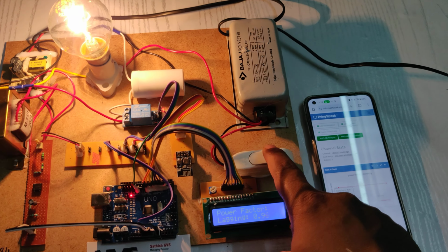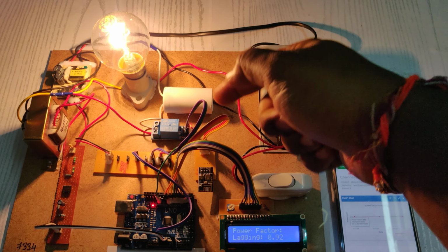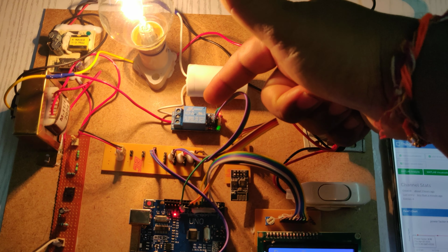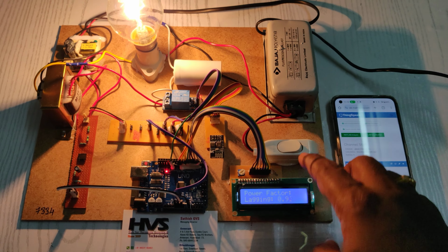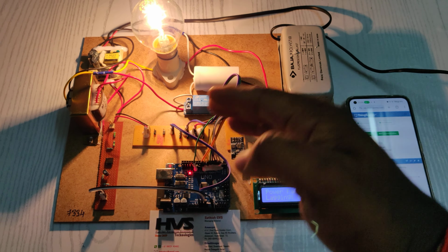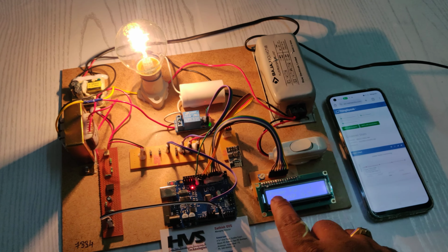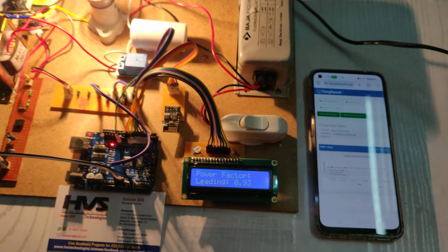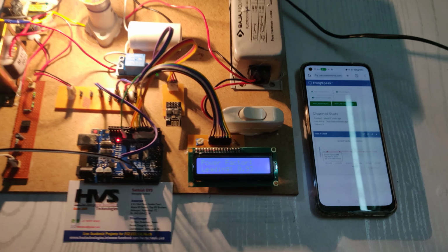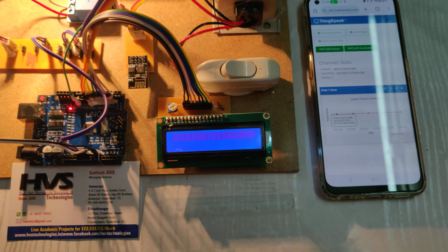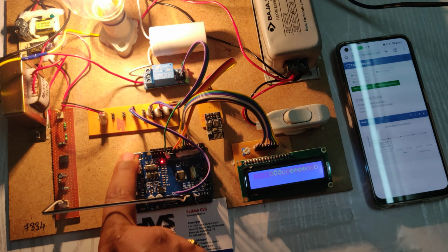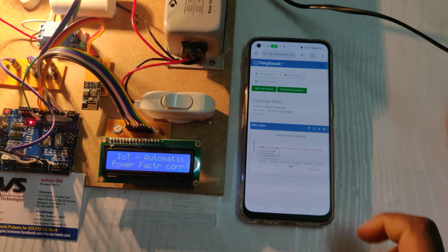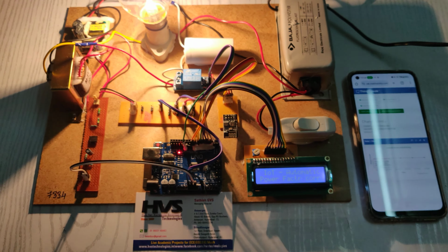Now when we switch this off, then only R plus L is detached. Only C was already attached by the relay in the automatic power factor correction method, so only R plus C will be there. As we discussed, C will lead the current waveform, so the power factor value will also be leading. You can check that. Right, it's a leading power factor now. Whenever we talk about the power factor, we should mention the power factor value along with leading or lagging. That is very important. If you recheck the system, then we get to know the power factor value directly.